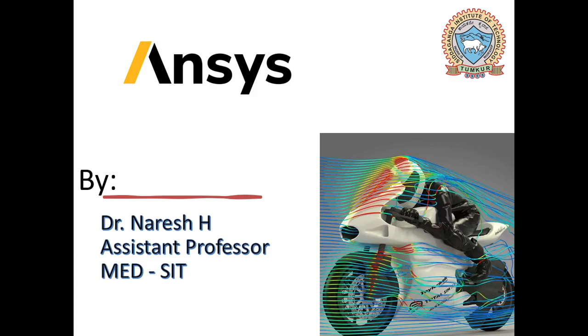In today's session, I am going to show you how to solve a stepped bar subjected to a thermal loading. In this case, I want to find deformation as well as maximum stress induced in the stepped bar subjected to only thermal loading. As in the previous videos you have seen, the bars were subjected to mechanical loading. So in this case we have only thermal loading. So let's begin.